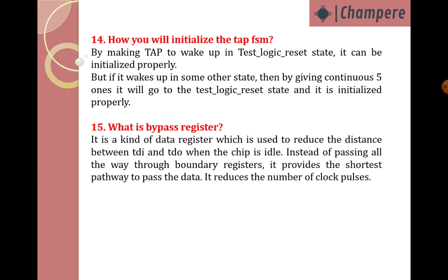But if it wakes up in some other state, then by giving continuous 5 ones, it will go to the test logic reset state and be initialized properly. So this is the way you can initialize the TAP FSM.